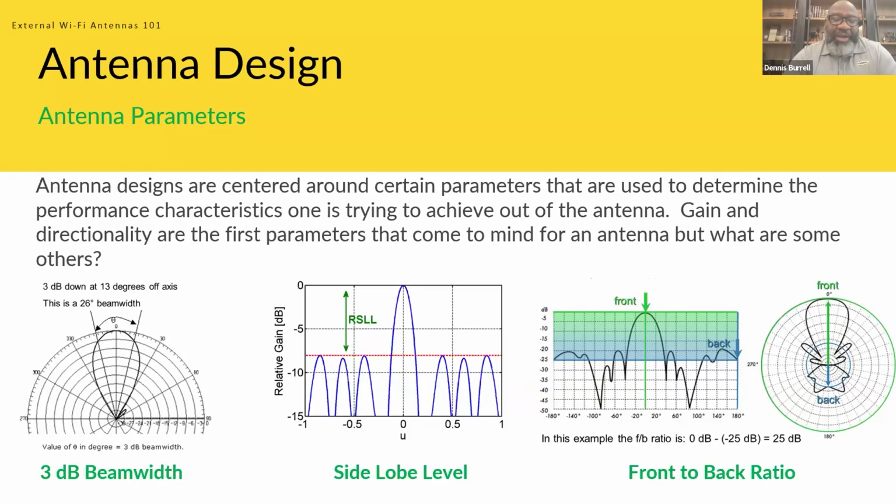And you want to have that main lobe level as the highest point, and then anything below that. So for instance, if you're designing in a high density network, you want those side lobe levels down at least 10 to 12 dB down from your main, so as not to have any interference as far as your high density design goes.